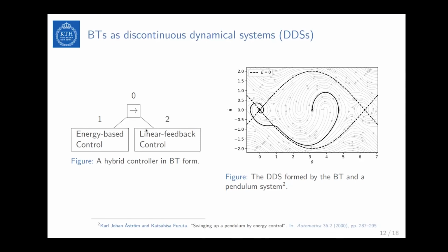It's still shown that behavior trees are optimally modular. So it reduces the cost of development and testing, and makes it more interpretable. With SAM, if we used a finite state machine, it would look like a spider web, which would be hard to interpret. So there you can already see one benefit of using behavior trees, but the underlying thing they represent is the same. They're both hybrid systems.